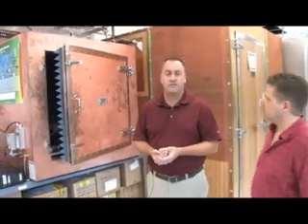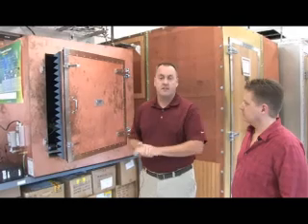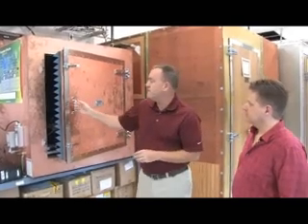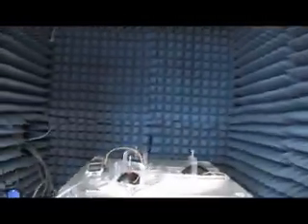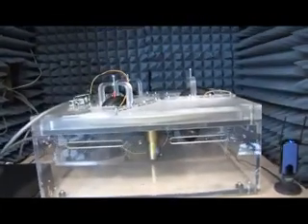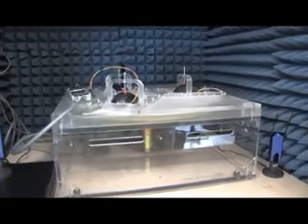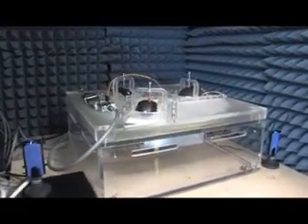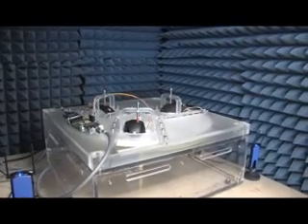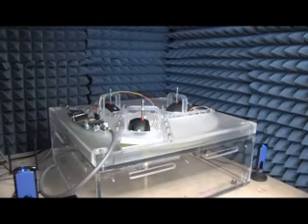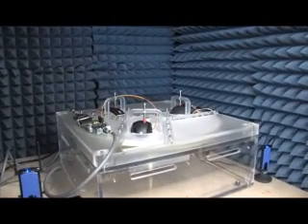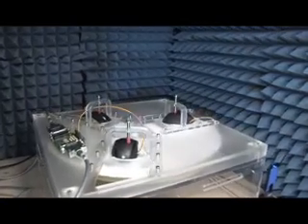And when we test our products at the assembly level, we need to check for different parameters. One would be like a range test. Another would be like interference testing. So what we have right here is an interference testing setup. If I open up the box here, if you look inside, what you'll see is a couple mice on a turntable. And we use this turntable to simulate tracking. So when it spins, the mouse looks like it's on a table and it's sending out data. We also have wiring harnesses attached to these mice. Now, we use that to simulate button presses.